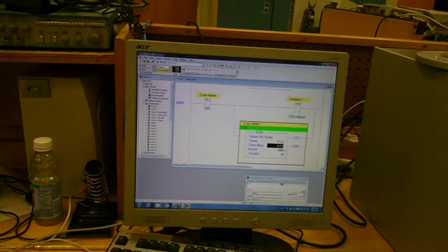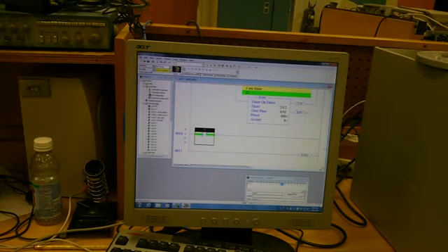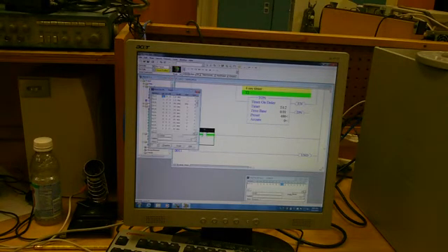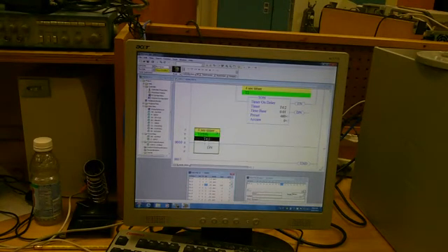All right, so where are we? That's the 4 second timer. Now we want one more. So we want this timer done bit. We'll bring in my timers again. And I got the wrong bit. I got the wrong guy. We're doing a delete of that instruction. Okay, so we want the T4:3 done bit, so we'll grab that guy. No, we want the :2 done bit. All right, so now T4:2 is done.